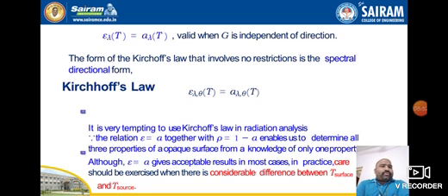Before that, the black body always has absorptivity 1. So there are three properties: reflectivity, absorptivity and transmittivity. When radiation strikes a material, part of it is reflected, part is absorbed and part is transmitted. Okay, so the sum of reflectivity, transmittivity and absorptivity is 1. So for the black body absorptivity is always 1, and for anything other than a black body it is always less than 1. That you should remember.